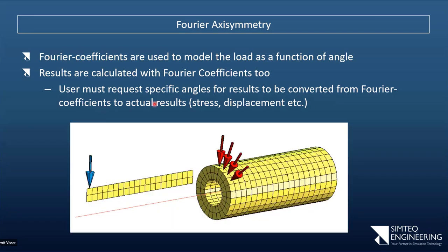So I can specify, argument's sake, the pressure varies as sin of, and that's one revolution, plus sin of double that frequency along there. And by doing that, I can model a complex load distribution using this approximation. It's not going to be exact for this kind of a load where if those are all the same load and then zero afterwards, I'll have some kind of an approximation where the load may do something like this and then spike and then a little bit of variation and come down again.